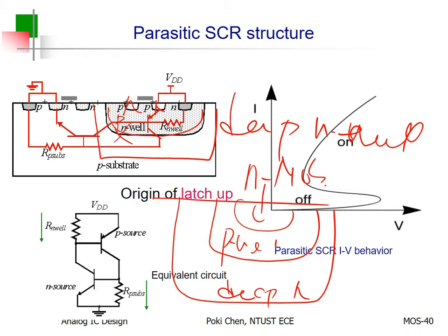That is almost the only way for you to eliminate the body effect for NMOS. I mean with P substrate. Okay? But nothing is free. You need to pay the extra mask cost for deep N well. It takes some money. All right?